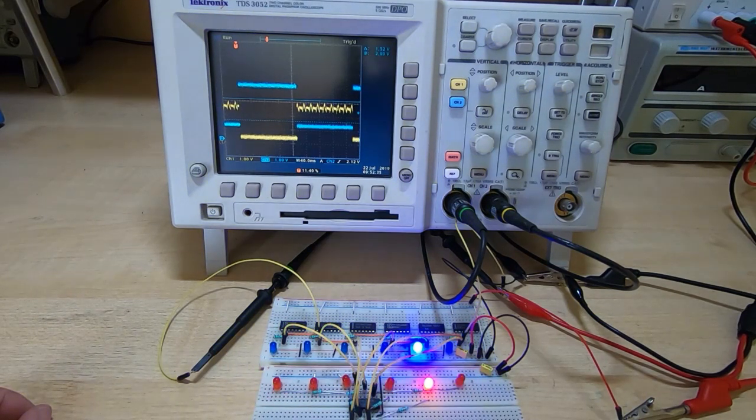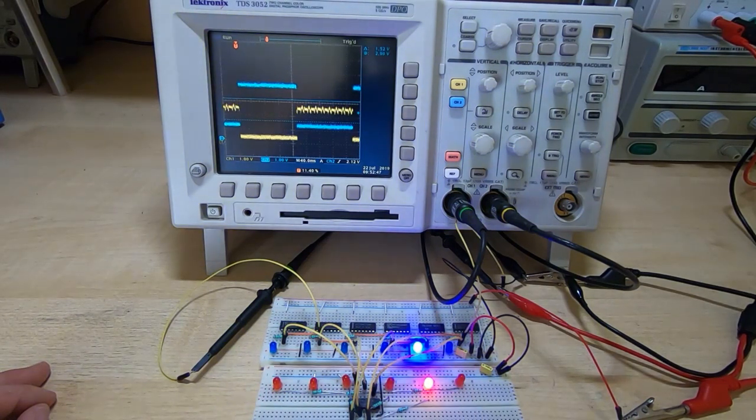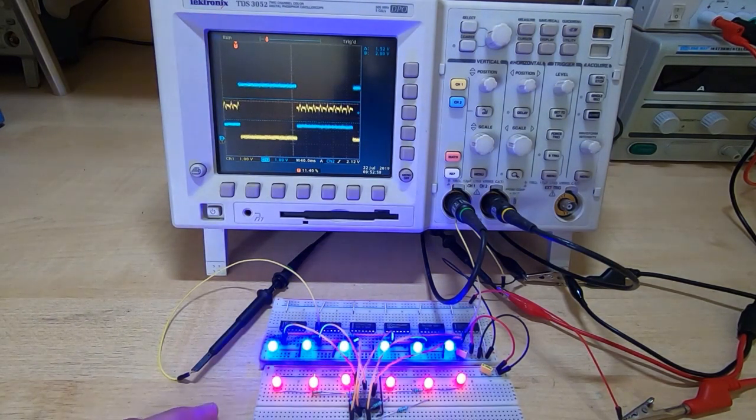It doesn't just come back to its full scale behavior, and that's something I think is not necessarily normally understood with these devices, that it's assumed that they're digital, so the output goes high or low, and it doesn't do that. It will give an output that's to a certain degree dependent on the input swing. And the problem there is it means you get all sorts of weird and wonderful behavior depending on the noise in the system, the voltage drop around the system.